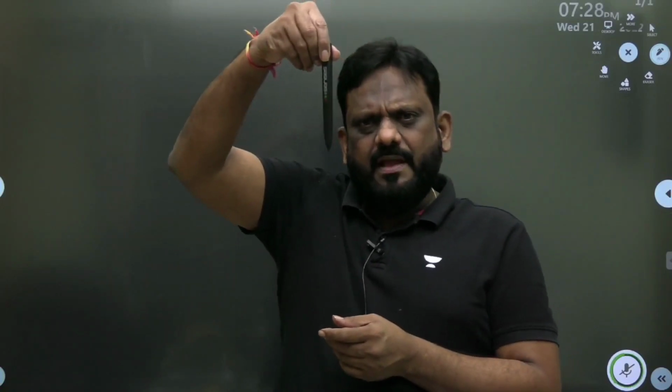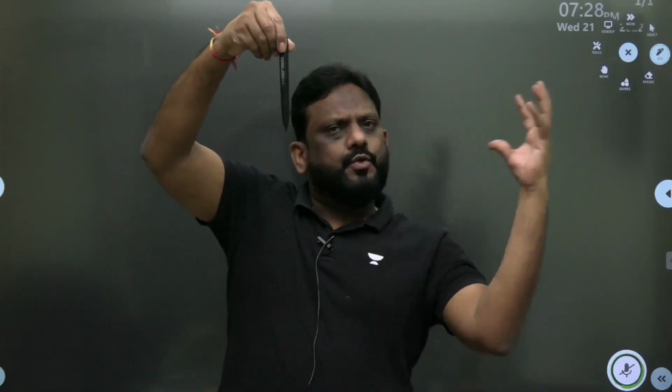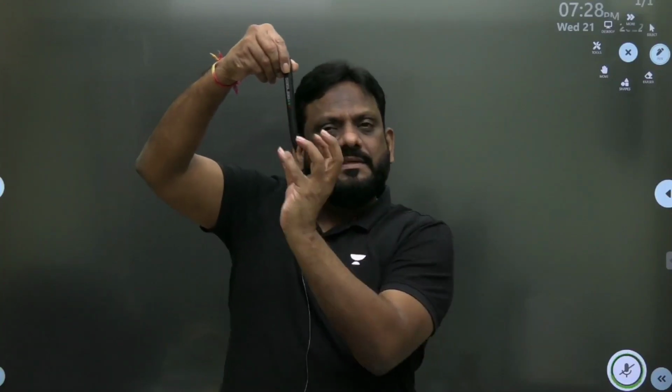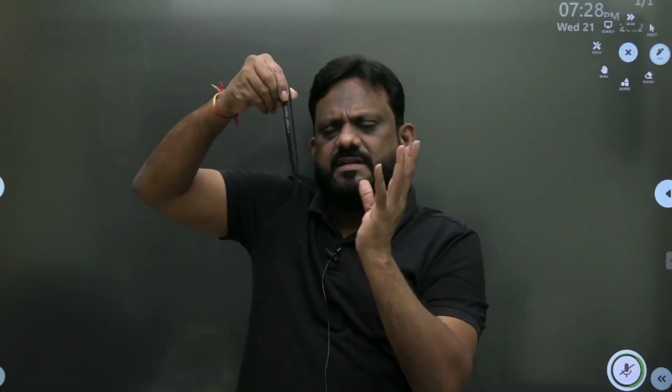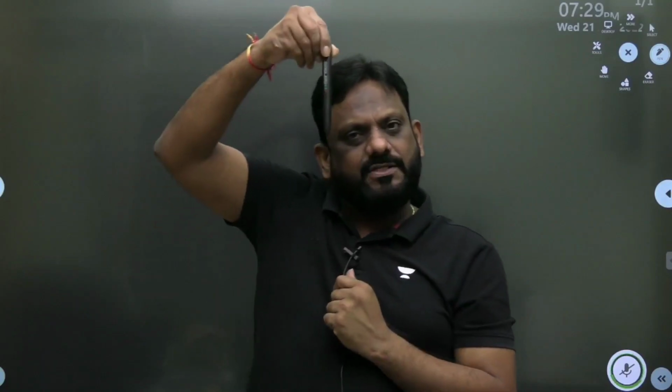Today I am going to do some experiments in this class. I have got a sling psychrometer, and a thermocouple, and I am going to do some experiments so that you can understand things rather easily. You should have a physical understanding of this. Dry bulb temperature is nothing but: let us take a thermometer and expose it to air. Please note that this thermometer is away from solar radiation and moisture content. The air is flowing, the bulb is not covered with anything, it is absolutely dry, and it is recording the temperature.